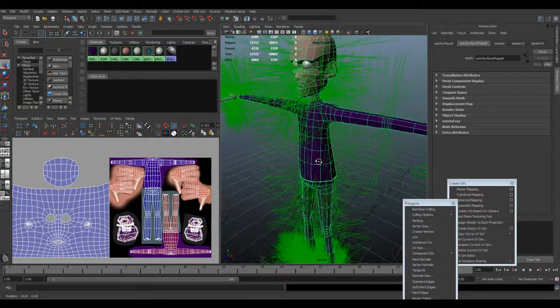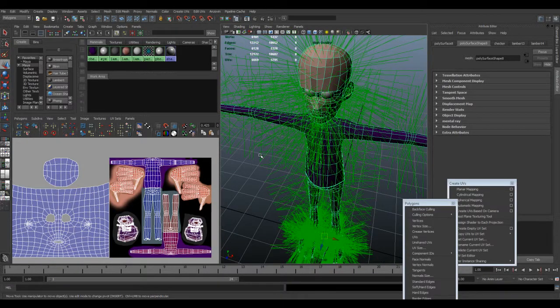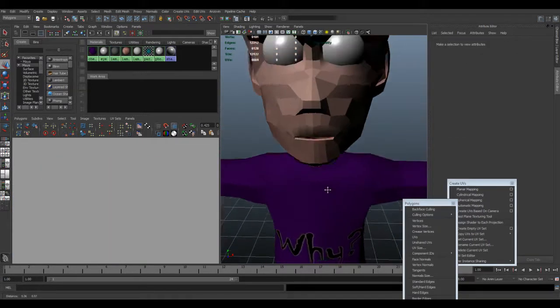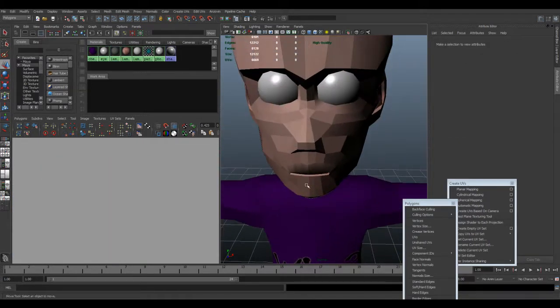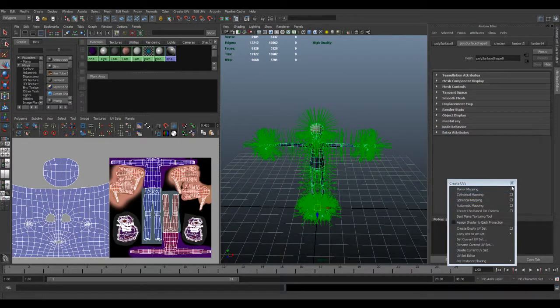Now, some of those faces may or may not be upside down. So, for example, if you've been modelling half of your character and you've flipped it and you haven't sorted the normals out, it's quite possible that you have got half of your mesh, your right hand side or your left hand side, with one of them facing inwards and one facing outwards, because faces aren't double-sided, they mainly have one side. If that's the case, you might get a strange line down the centre of your character, a line like this where you've got problems with the normals. Now, there are ways to manipulate this.